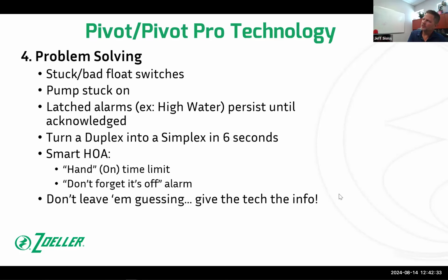We want to make sure also that people understand a couple of things. When you're talking to a contractor, I don't know if you guys talk to contractors directly or not, but when you're answering questions about the panel, people need to know in the back of their mind that this panel behaves differently than a panel you've been used to. So if you walk up to this panel, it's installed, the pumps are there, everything's there, and you start lifting switches and you don't do so in order, both up and down, the way water would lift them up and down, the panel is going to give you an alarm.